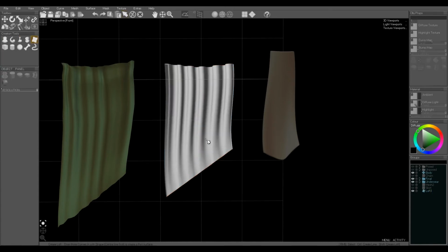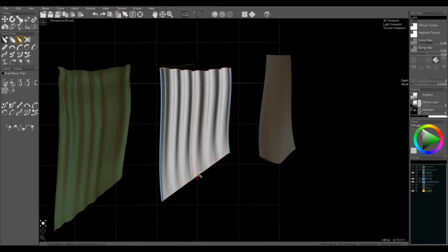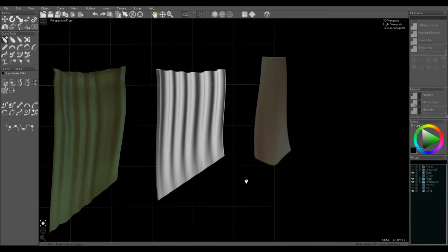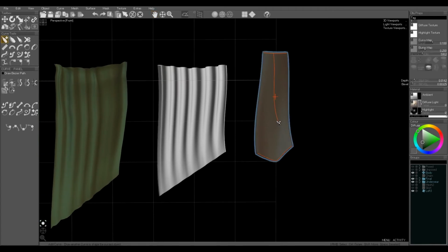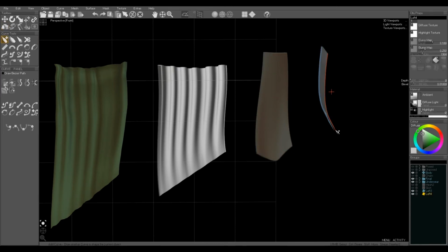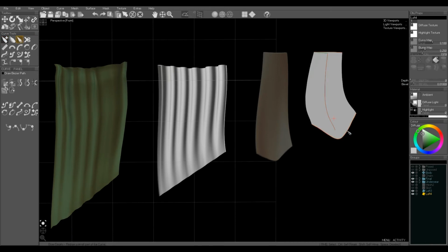Using redraw smooth curve to tidy up any curves. The curve rulers are very useful for reshaping small parts of a curve. And now the tag. Again, we're going to draw with a lathe along the length of the object. Then draw a top and a bottom. Use the rulers to tidy it up.